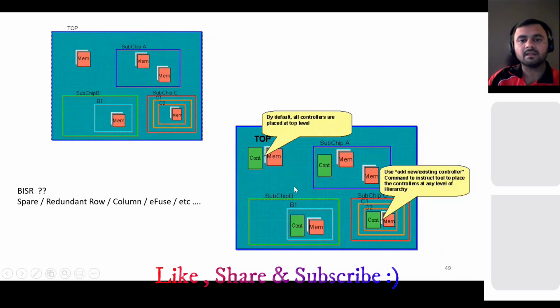generate the test data. But suppose some of the memory gets faulty, like you later figure out that some of the memory has a fault. How do we repair that fault? In the industry, we use built-in self-repair. Basically, we have some spare redundant rows and columns inside the memory, which we don't use for normal functional use. We just keep them as they are, so that if we discover any fault later on, we can use those spare cells, use the spare cell address instead of the faulty address, and easily correct it.